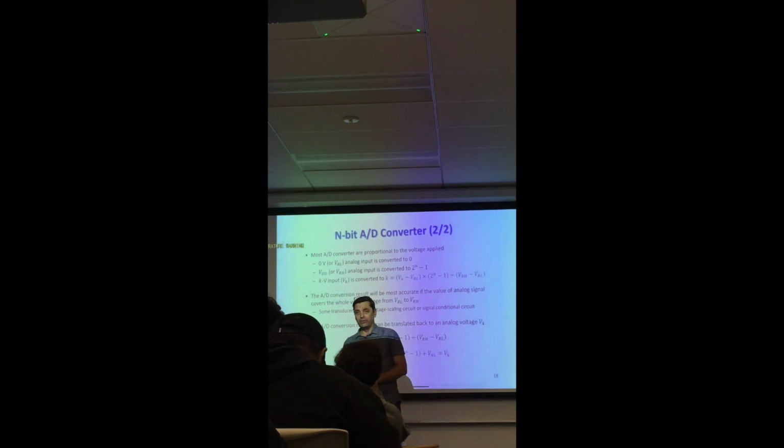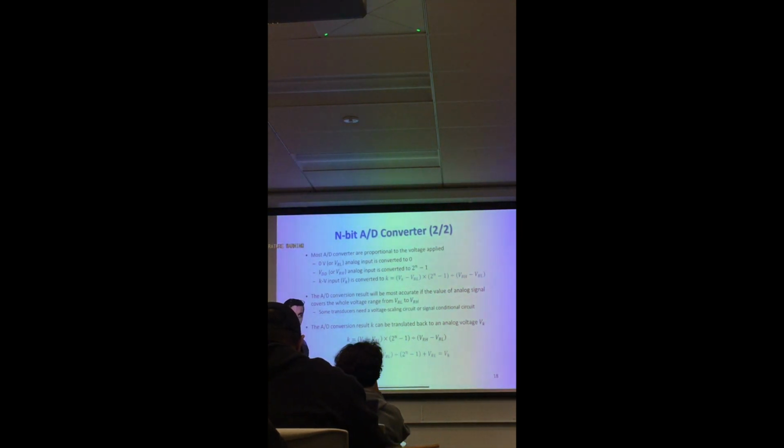So, for example, one way to increase the resolution given a fixed precision, right, 12 bits, is this: you want to increase the resolution of that voltage, but you know that your voltage will be between 1 volt and 2 volts, right? You can do it by simply changing the range of voltages that you will be resolving. So these 4096 levels will be between 1 volt and 2 volts, so the resolution will be increased compared to the resolution if your range is from 0 to 3.3 volts.